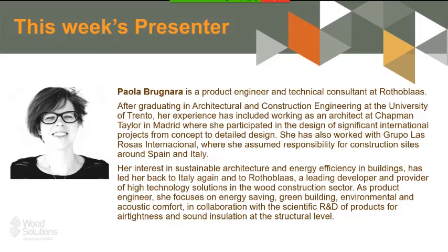Yeah, and coming back to my experiences in Italy and to these recent experiences here in Australia, where we measured both a mass timber building after it was built, the Latrobe, and also a stick frame building, the 5-story green apartment block in what is called Parkville, in both cases the results from on-site tests were better than what was predicted. So there is caution from the acoustic engineers in designing with timber correctly, because they had less experience. Now some of them are starting to have significant experience and test results. But anyway, this precaution has resulted in better than estimated outcomes, which is the correct way to go, of course.